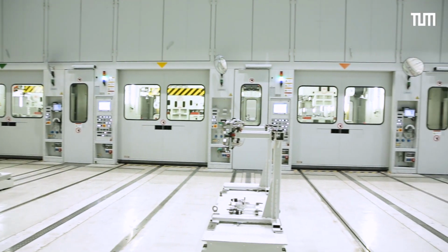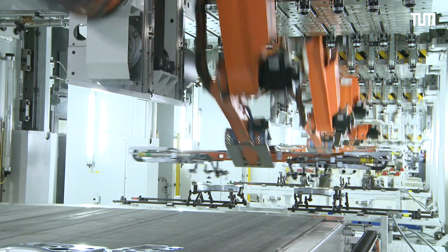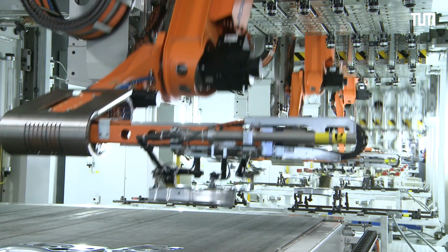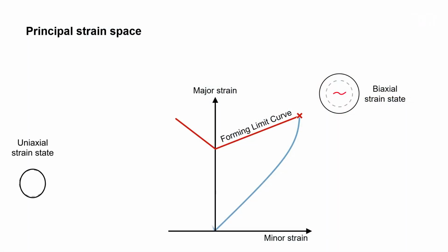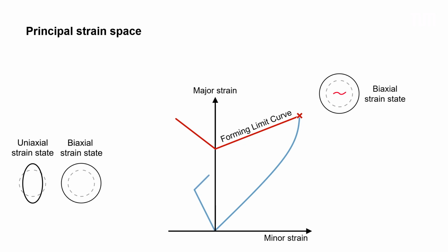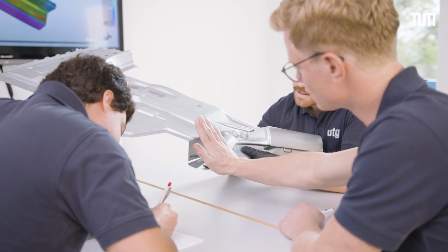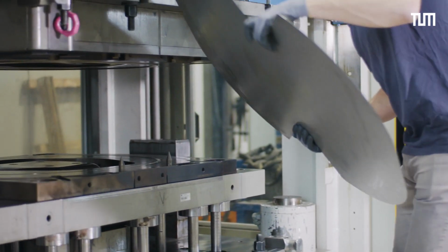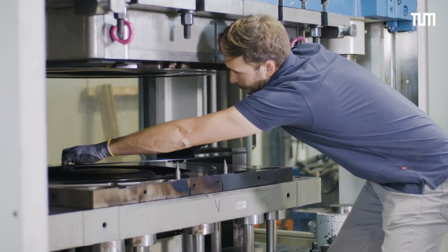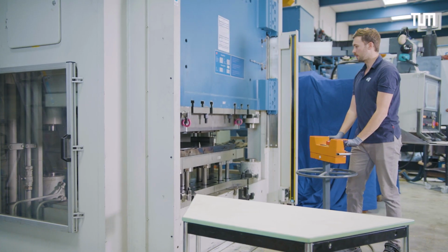The reality of a forming process, however, is much more complex. In standardized methods, only linear strain of a component is considered. However, in multi-step manufacturing processes, a component is subjected to various load directions. According to the GFLC, Generalized Forming Limit Concept, it is possible to assess occurring nonlinear strain paths with regard to failure.